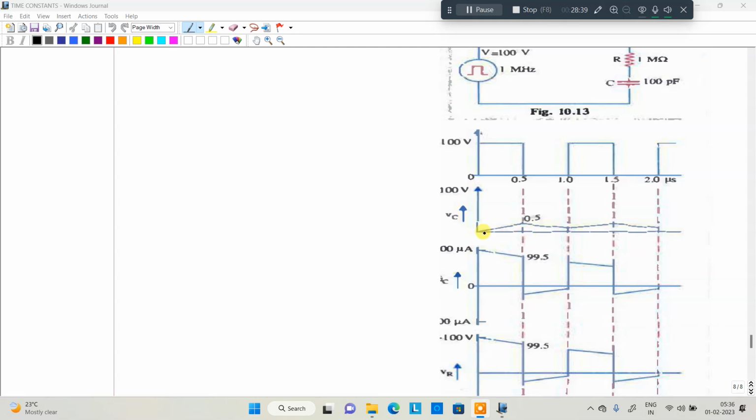Once it is completely charged, it discharges again. Then again it charges. That means whenever using long pulses, some charge will always be present on the capacitor, increasing or decreasing. It does not reach zero. So that's what the current and voltage waveforms look like for long periods. This is the resistor voltage waveform.